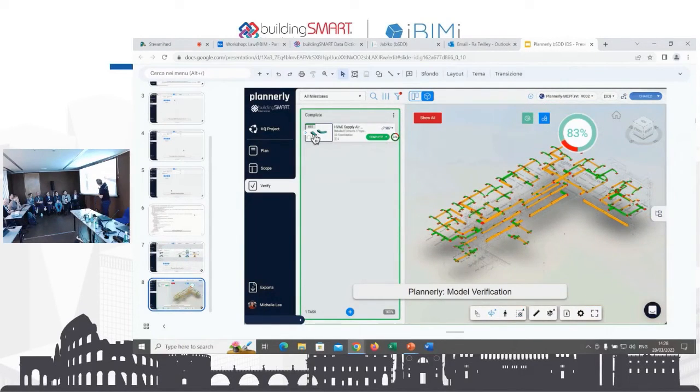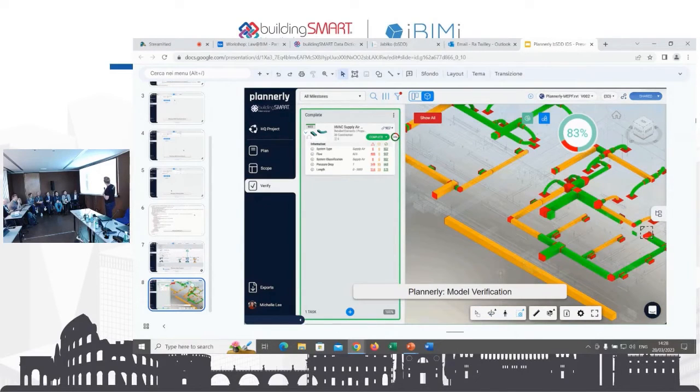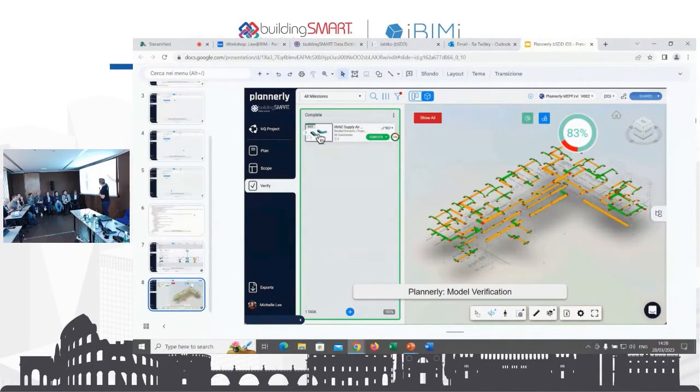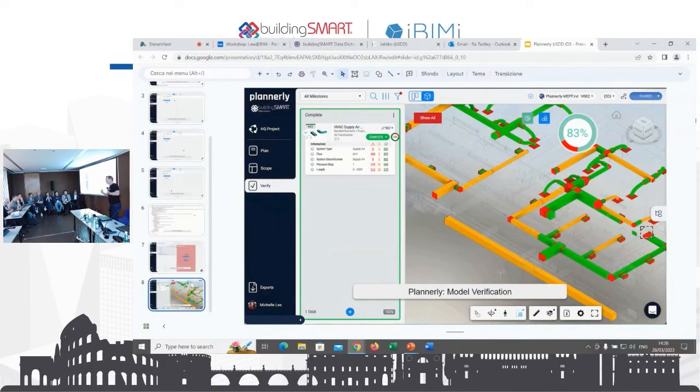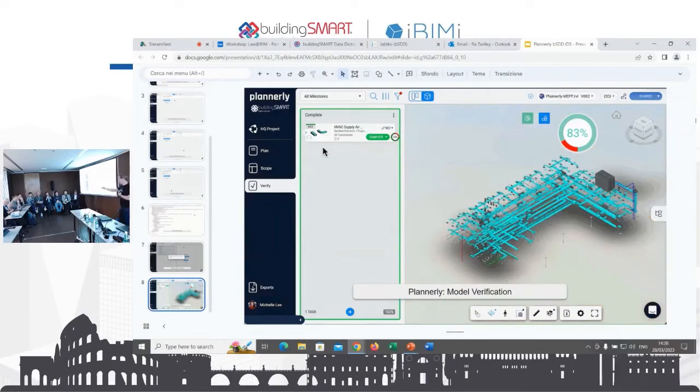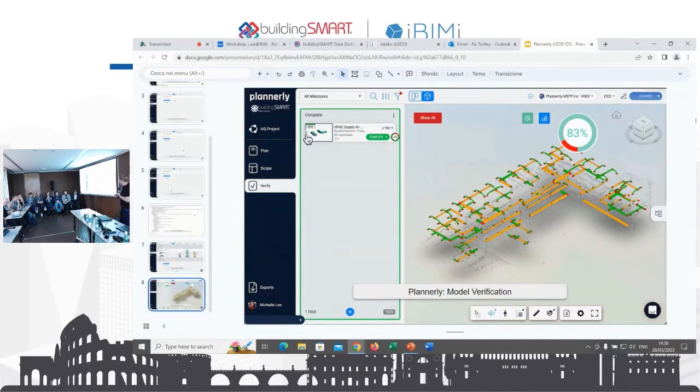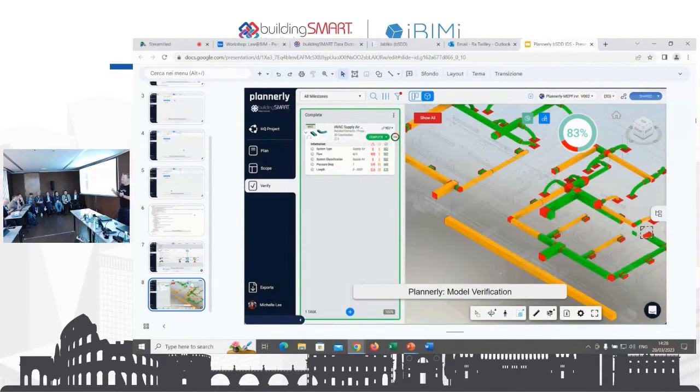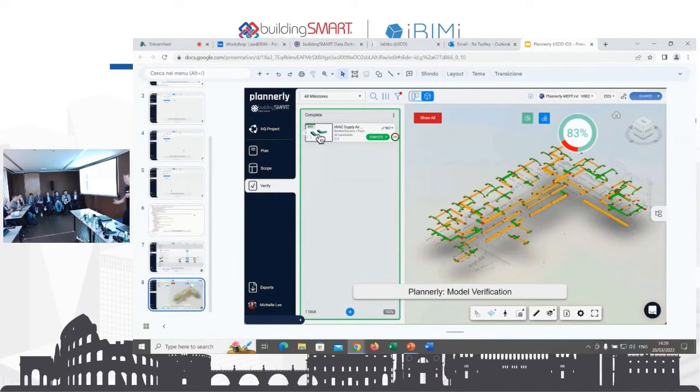The model is then linked in, whether it's coming from Autodesk Construction Cloud, as this one is, or whether it's just dropped in. It automatically links up and verifies whether the properties are not just there and matching the bSDD, but also checks the values. Do they meet those requirements, yes or no? Color coding the model makes it really visual and easy to understand.